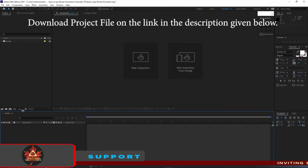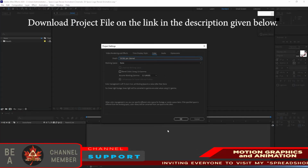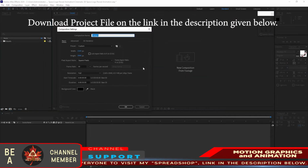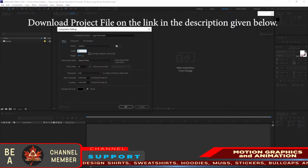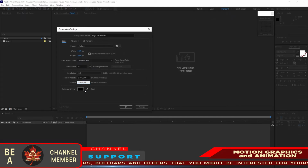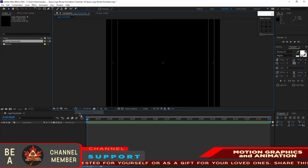Before we start our project, we will change this to 16 bits in order to have better color accuracy. Go to Composition panel and create a new composition. I will name it logo placeholder. I will change the width here to 1420. The height is 1600. The frame rate is 30. The duration, I will change this to 8 seconds. Click OK.